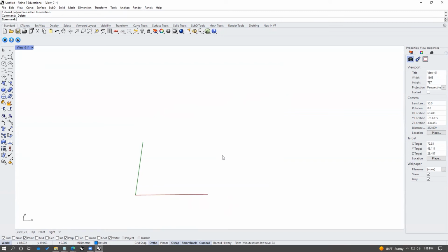So this type of geometry is called a mesh, whereas surfaces are defined mathematically, as we saw and discussed, relating to Bezier curves and then the development of surfaces mathematically. One nice thing about a mesh is that it's lightweight computationally, so it is efficient to compute. That's because it is made up of discrete entities. There are only a fixed number of points versus being mathematically or infinitely defined.